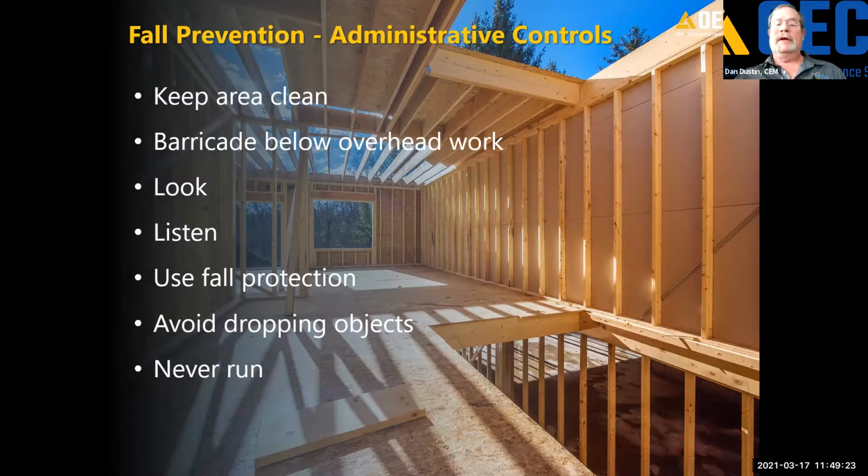Now, there are some exceptions that are right in the standard. One of them is for scaffold builders. During erection and dismantling of scaffold, they have a little more leeway because during erection and dismantling, there's very little to tie off to. But for most of us, if you're working from that scaffold, you don't have that provision. Does that answer your question?